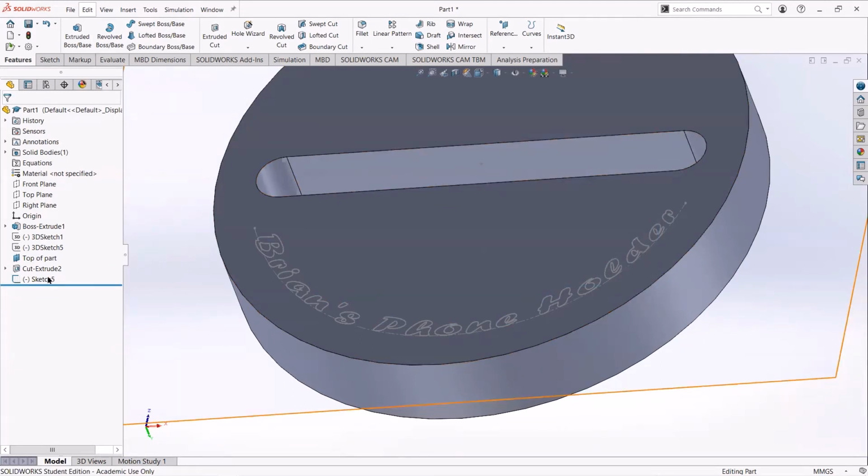And we're going to do that again, like I said, except now we're going to extrude the base, not cut it. So we're going to select the sketch, and actually while we're at it, select the sketch and then click it one more time, and that'll allow you to change it. So that'll be maybe label, and then that way you know what that is doing.